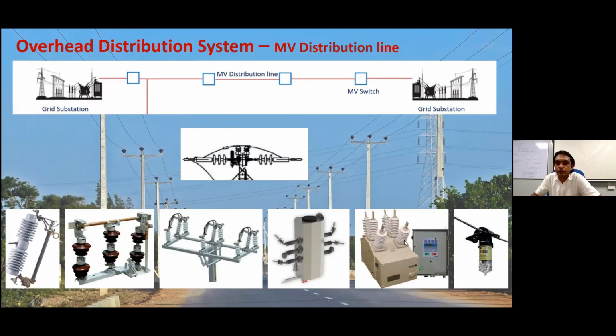This is also very useful for temporary breakdowns. That means if the line touches a tree and is temporarily connected to earth, then it's a temporary fault. The control box detects it and sends a command to the switching mechanism to open, and we wait some time and it recloses. Therefore its name implies auto recloser. Once the fault is eliminated from the line, it can close permanently.